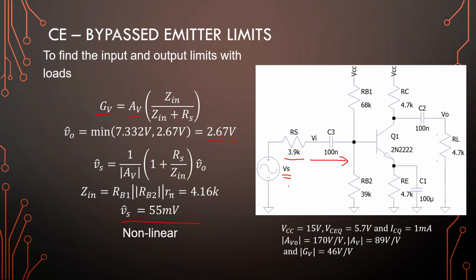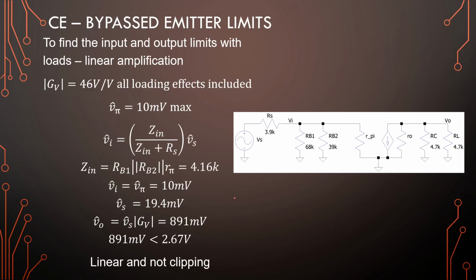of this system when everything will be linear, when our input and output will be the same? Okay, no extra spectral components added due to the non-linear effect of this transistor. The answer is quite simple. We see V pi, or the delta VBE, as being small, around 10 millivolts peak. So now we just rearrange all of these equations so that V pi becomes our input.